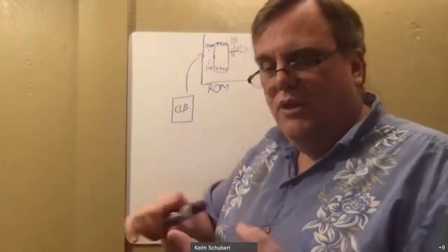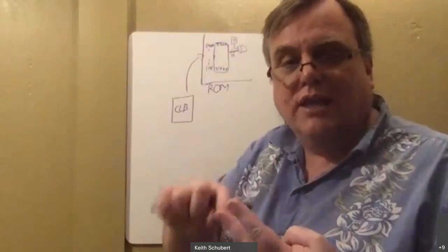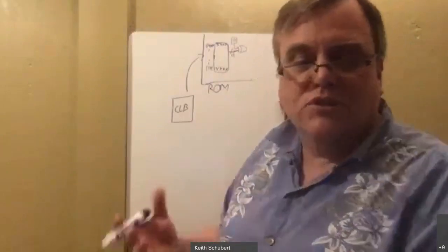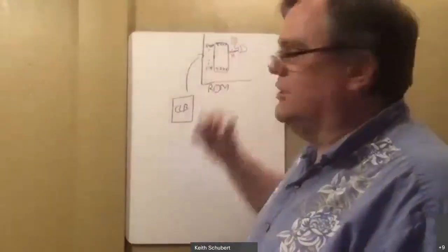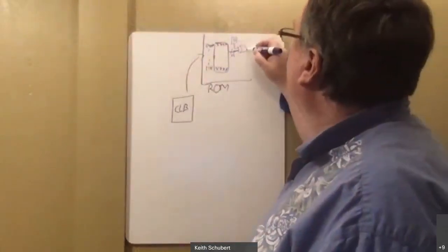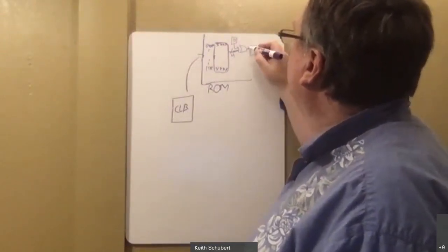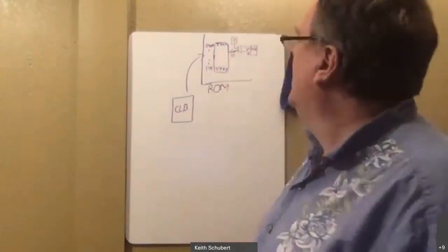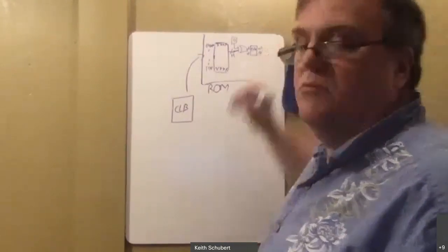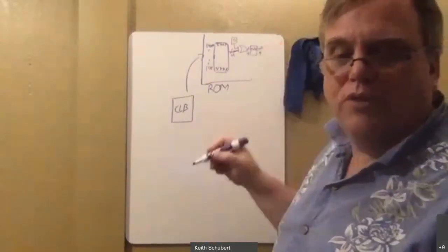Remember how we had sum of products and product of sums, but we also had negated sum of products and negated product of sums. This bit, if it's 0, does sum of products style, or you can just flip that and it flips everything in the chart. That's another parameter that's in, and then on the simplest one this goes into a D flip-flop, or a series of D flip-flops since it's 4 bits. So there'd be 4 of these D flip-flops. I'm just going to show that by a single one here, and it's understood since it's 4 in and 4 out, there must be 4 of them here.